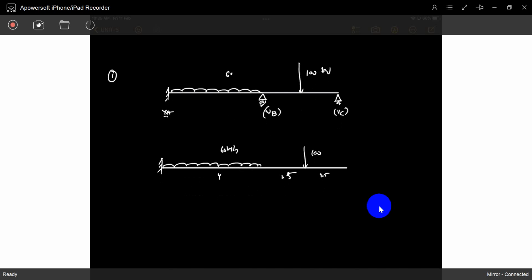Deformation means, if VB is in this direction and VC in that direction, those are the forces, not the moments. So you have to find out the deflection in the VC direction and the deflection in the VB direction. Later you find out the flexibility factors, multiply with these two unknowns, and the final deflections in these directions are 0. Those two complement each other. Is it understood? That is my logic.